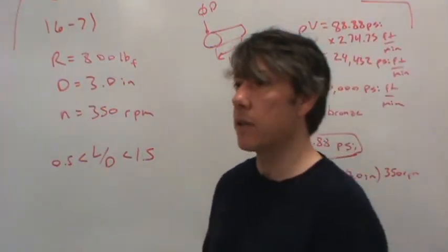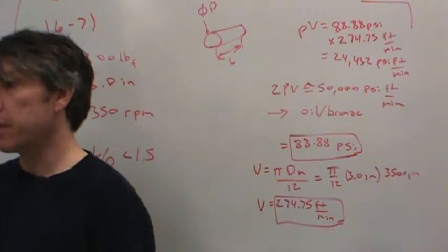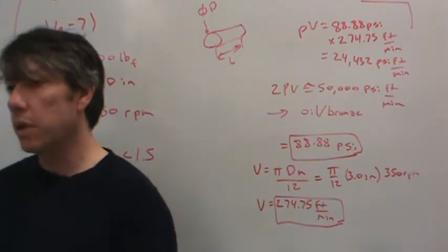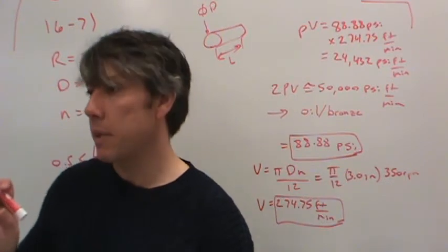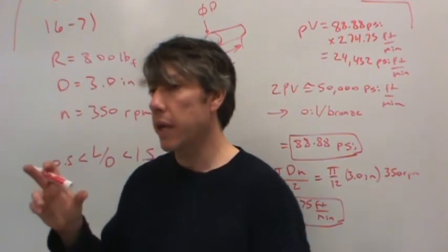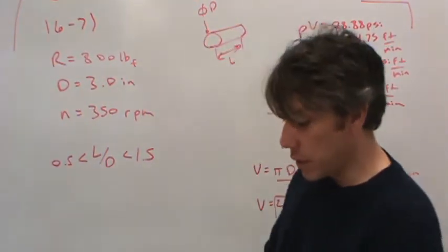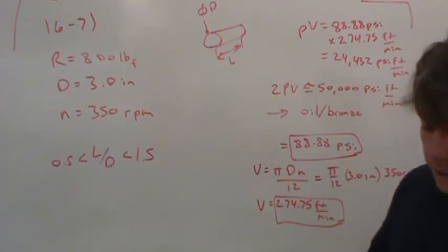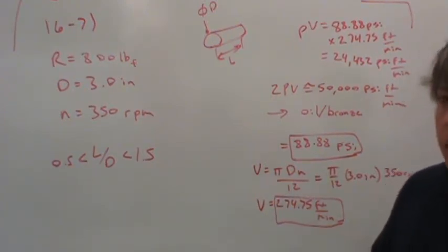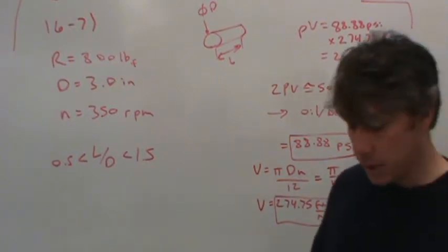Basically what he's saying is this is a complicated problem. But this chart gives us a minimum amount of clearance. And so you have to tolerance the journal and the bearing such that you always have at least that minimum clearance. Because if the journal were to heat up and the bearing didn't, the journal is going to expand and it might seize. We need to avoid that. So really the last step in this procedure for our class is to look at figure 16.4 and decide what the clearance should be based on this. Now this is a minimum clearance.